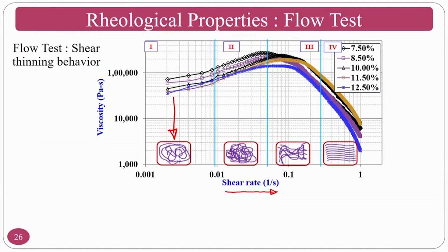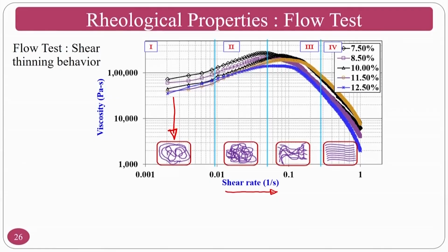Gradually the viscosity of the fluid will increase, because of the unity of the polymer chains along with the other ingredients and the abrasive particles. But any polymer chain or any material has its own strength, beyond which it starts breaking and aligns in the direction of the motion of the top plate. So, that is why in section 1 it is increasing because of the unity of the polymer chains.